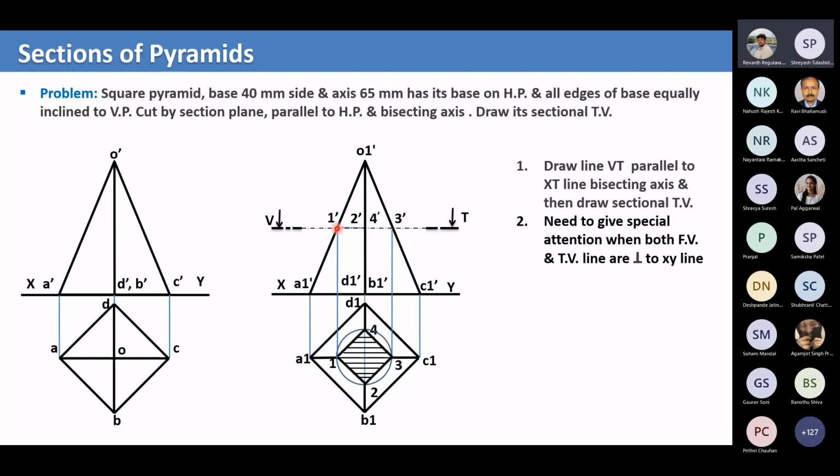So that's why we project here, we bring it down, and then with this as a radius, here there is no O1 written, but you have to imagine that the center point here is O1. So from O1, you should take this radius and cut this arc here and here, and that is how you get 2 and 4. I hope everyone understands why we are taking the arc and cutting. If anyone has a doubt, you can bring it up.